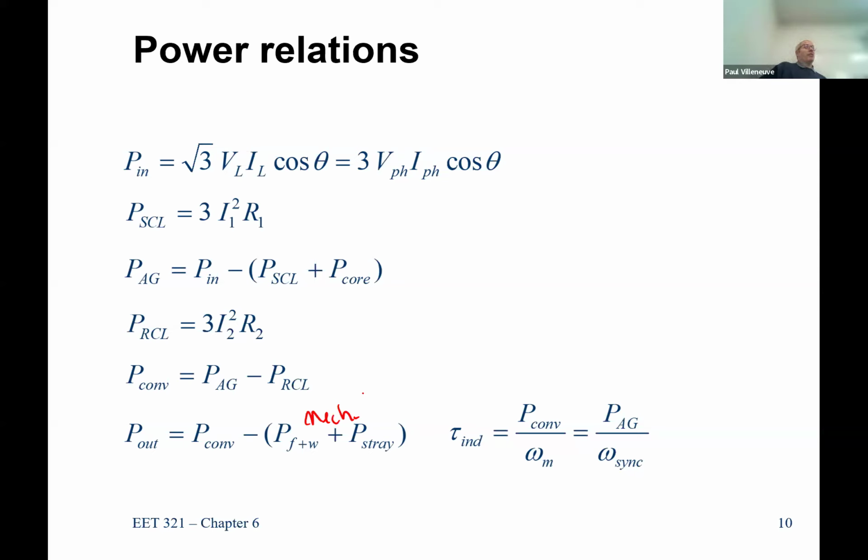And then the friction and the windage. The windage part of that is how smooth the shaft is. I don't know if anybody's ever seen what an induction machine shaft looks like, but it's not the smoothest, right? It's iron, kind of rusty because it's just made out of iron, but it isn't perfectly smooth. You know what I mean? You can rub your hands on it. I'm not saying it feels like sandpaper, but it's not polished like a mirror where your hand slides right over it. So you can polish your shaft if you want a little more efficiency.